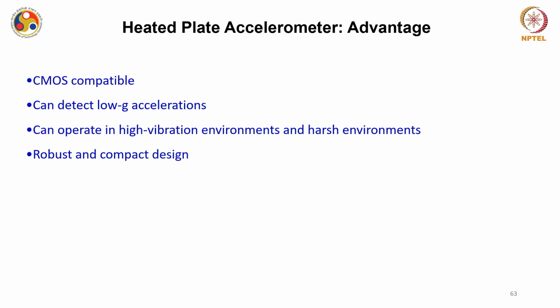Another advantage of this kind of device is that they are CMOS compatible. You have seen that everything is fabricated by micromachining silicon. They can detect low g accelerations, and can operate in a high vibration and very harsh ambient. Till now we have seen that if you require very harsh ambient conditions, mostly the optical devices are capable, but these thermal devices can equally be compatible with this kind of conditions.